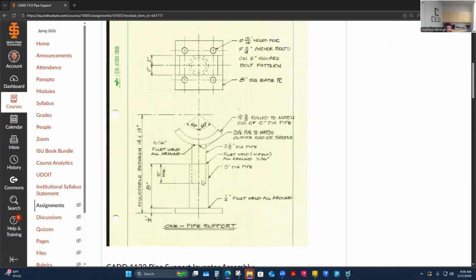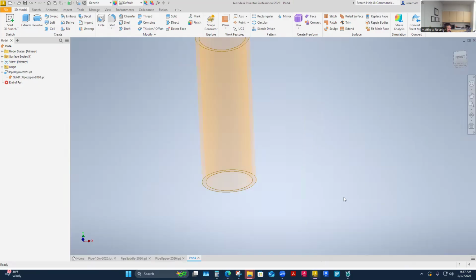What I want to do is build my part so that it lives in this relationship, that it's already overlapped 3 inches from that on that derived part. And there isn't a plane there where this one kind of starts, if I think of that. So I'm going to establish a plane there, the same way, only it's a little different way of establishing a plane. I'm going to say, here's my part. I know it's all kind of goofy and curved up there, so I'm working from this nice square end of it, kind of strategically a little bit.